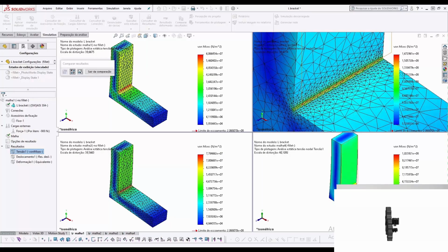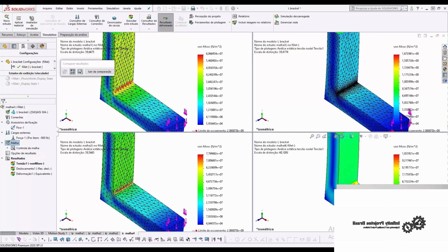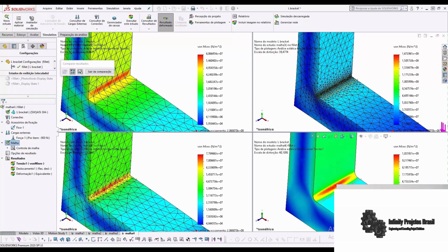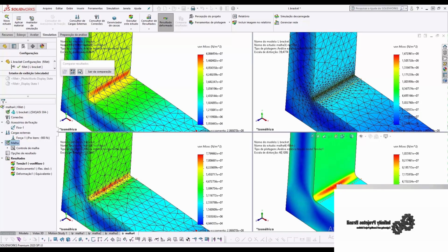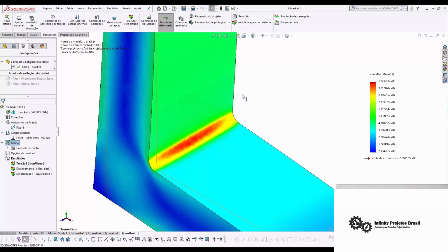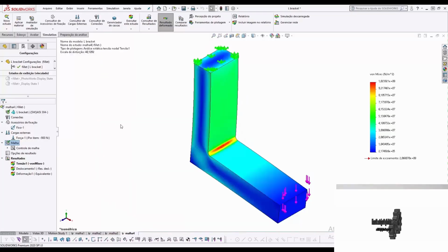Here I have contact force and connector force. In our case we use the reaction force, which is how much it will react in relation to the applied force, and here it is 9514 newtons. I can ask to display the resulting forces. I have this arrow with a force of about 900 newtons, so we can conclude that this support keeps the whole structure in balance, without any kind of setback.